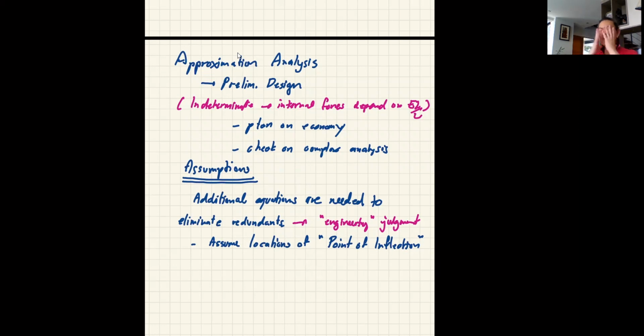You know, I used to give a lot of weight to the point of inflection in the past, but only like 10% of the students could get there, and it's a very important part of the structure. The point of inflection is the point where your moment curvature changes, right? From negative to positive or vice versa, which means at that particular point, moment must be 0.